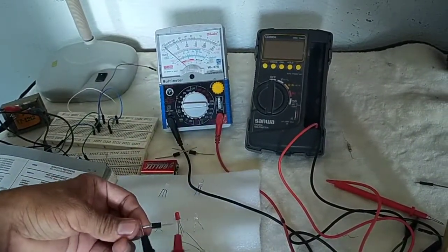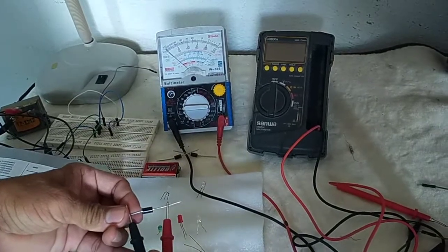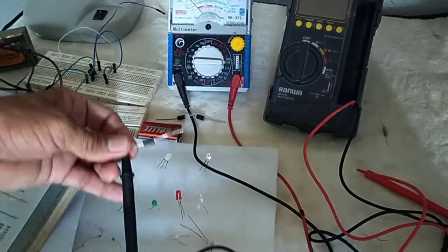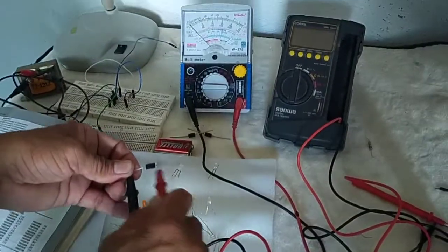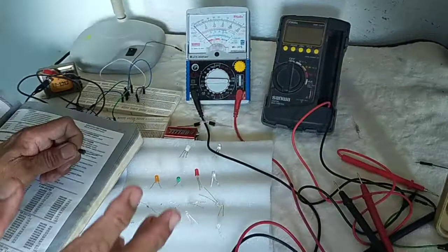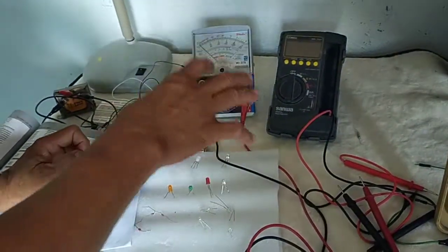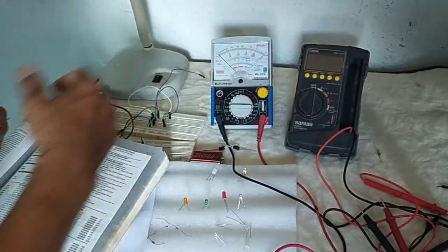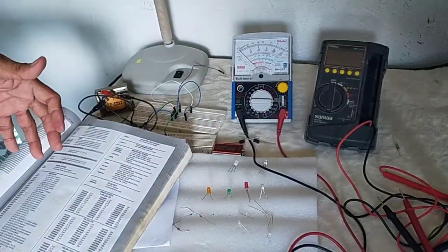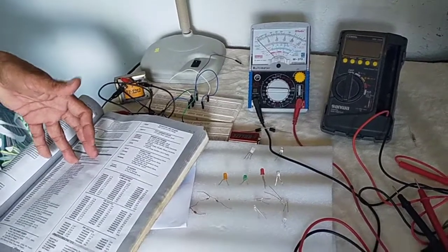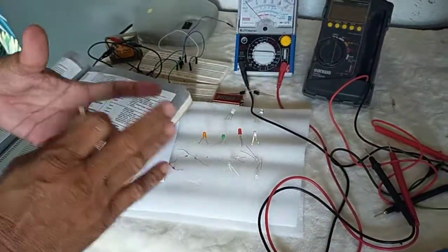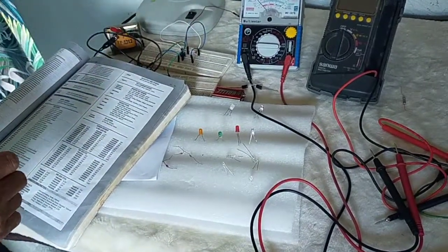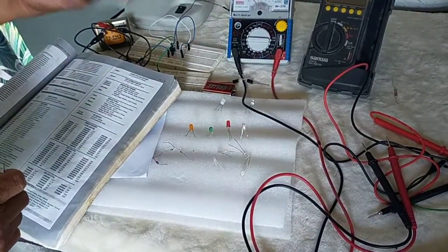We have here reverse bias because this is the anode actually, which is reverse in polarity with the battery. So, walang deflection because the lowest peak inverse voltage for this rectifier diode is 50. And the maximum is 1000 based on the rectifier diode manual here. No? So, there should be no deflection in the reverse direction for the rectifier diodes because the peak inverse voltage is 50 or above.